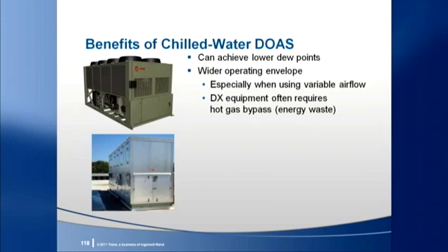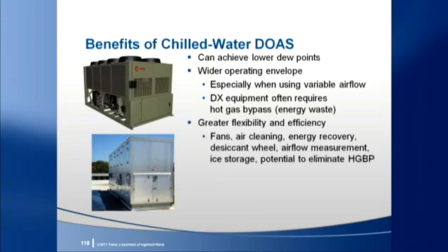This buffer is a great benefit if demand-controlled ventilation will be used, since this results in varying airflow across the coil while simultaneously controlling the wide range of entering air conditions. Another benefit of using chilled water for the dedicated outdoor air unit is greater flexibility and an opportunity for even higher levels of efficiency. For instance,